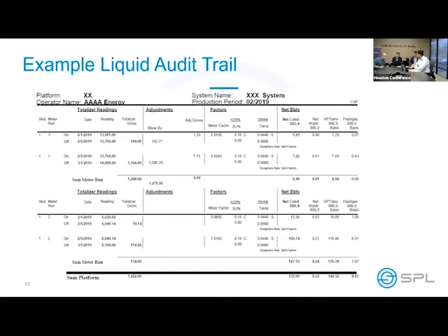The shrink factor you get one of two different ways: either from a physical shrink in the field, where you're literally doing what we showed in our little video. You collect a sample, pop the top, you have your starting and ending, and get a shrink factor off of that. Or, what I think is getting more and more commonly done, is through process simulation modeling. You get a good composition of your product, and from that you can calculate what your shrink factor was.